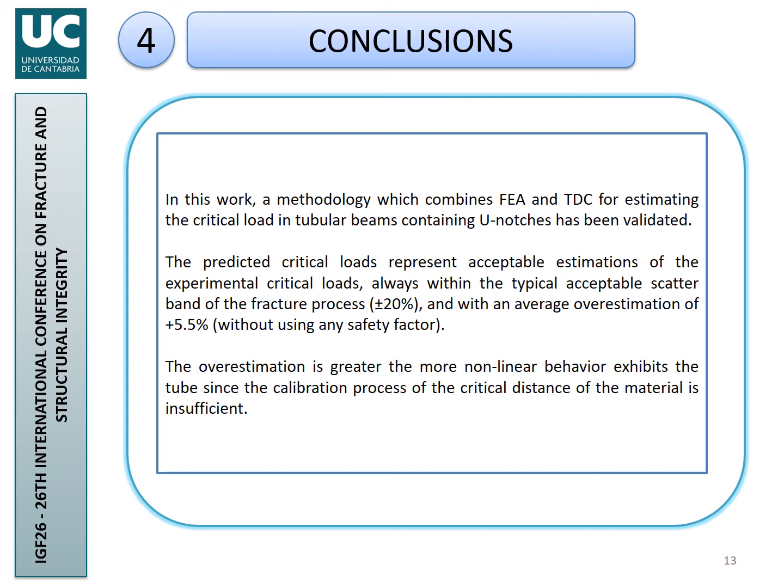So, with all this, the main conclusions are the following. We have combined the theory of critical distances with finite element analysis for estimating the critical loads on tubular beams containing U-notches, actually through thickness circumferential notches.